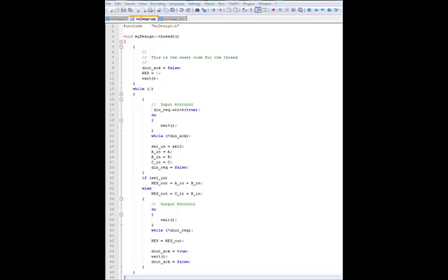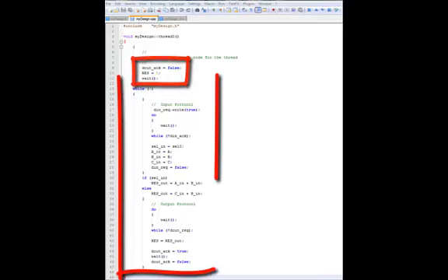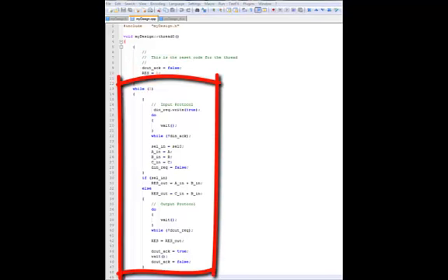Over in the CPP file, we see the actual functional code of the SystemC thread. This function is split into two main pieces: an initial chunk of code that represents the reset code, and a while(1) loop that represents the standard operation of the thread.